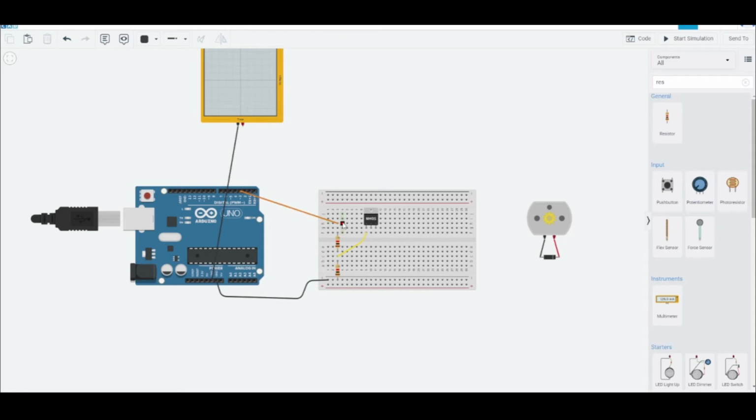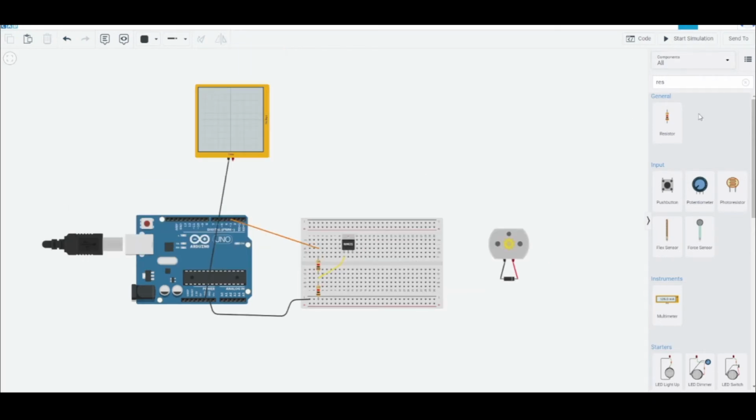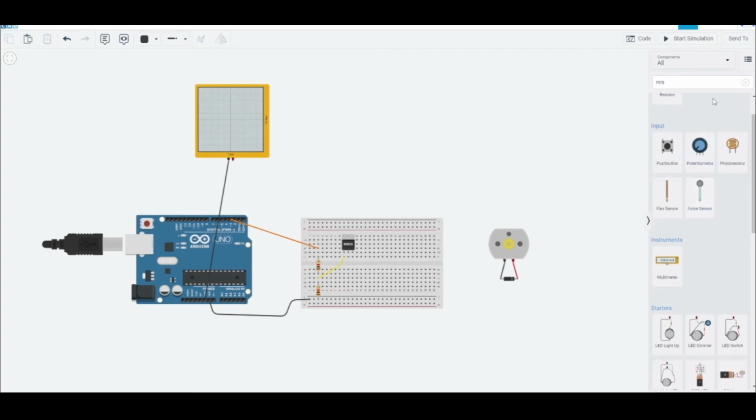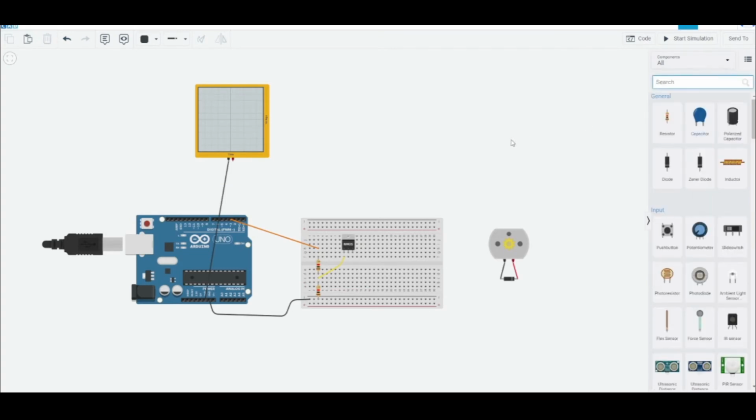So the PWM signal is going to come to this node. It's going to be divided by 2 here. That signal is going to be 2.5 volts at its peak here. It'll go into the gate, and the gate is going to switch the source onto the drain. I have a video on this where I kind of loosely go over transistors that you might want to check out if you're unfamiliar with the workings of those.